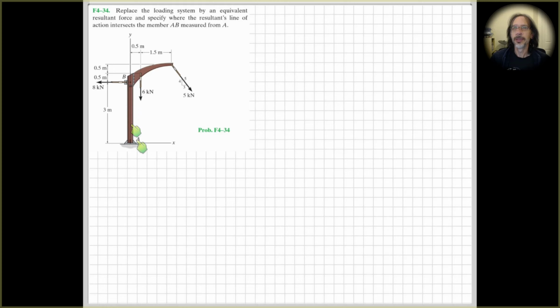single force. To provide some context for this, the intermediate step that I just explained, where we find the force normal and the force tangent or shear force here plus the moment, we would use those to enable us to design the connection between this structure and the ground. So we'll probably have to bolt this into the ground. We might have some welds around the bottom here to the plate.